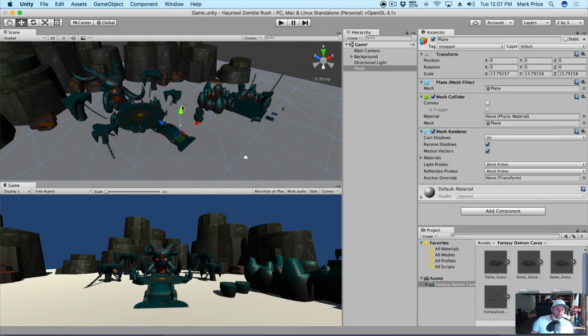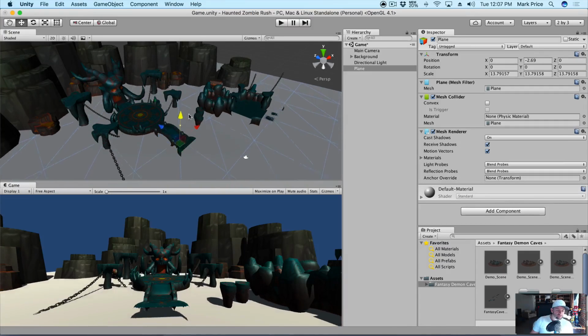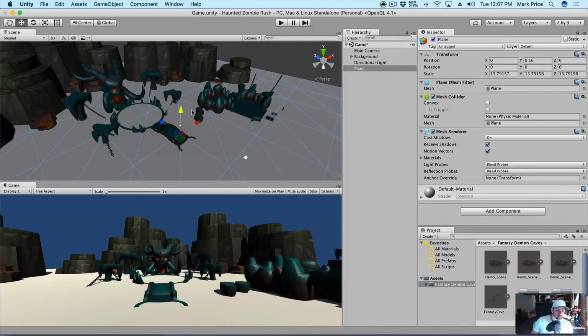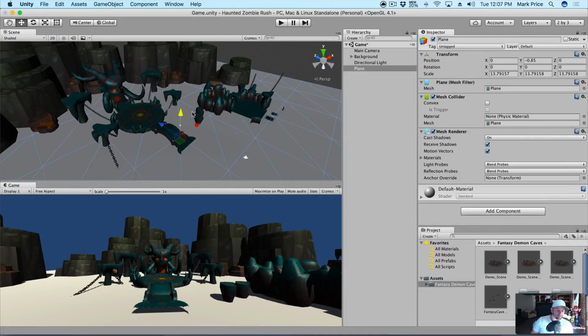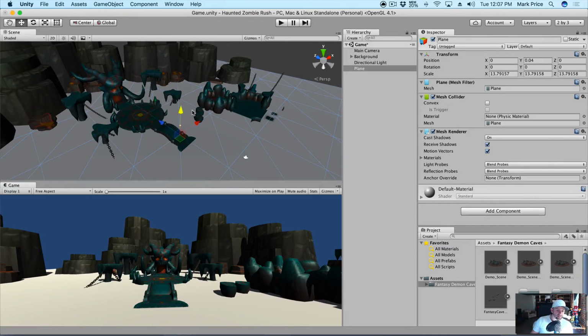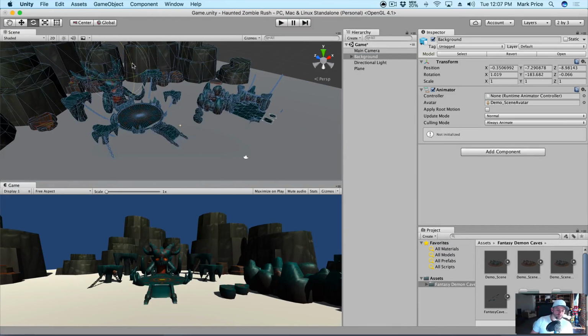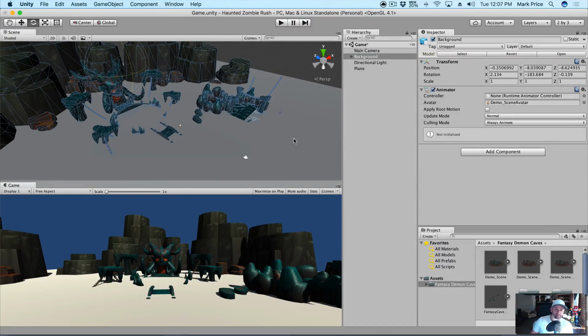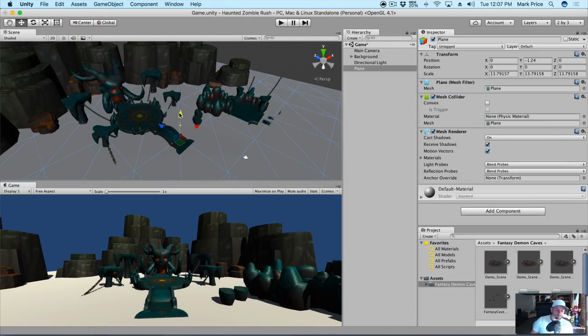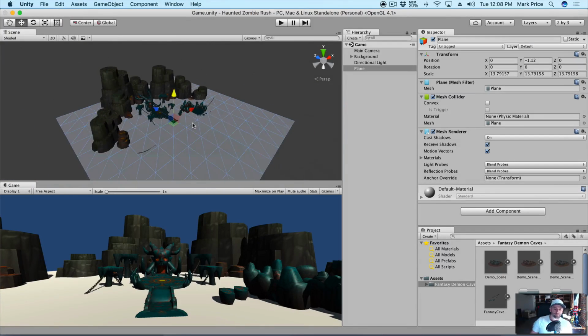It's looking real good. And then I'm going to bring it down until it's at a point where it looks like lava, which I think is right here. We need that front platform kind of into it. In fact, we can select our background here and E to rotate. Let's just rotate it downwards a little bit, slightly like this, to have an angle. So no matter where I put it, it kind of digs into the lava, which is what we want. We don't want to see edges. Cool. Okay. So what we're going to do is we're going to get a texture on this lava, and then we'll call this video done. So how do we do that?